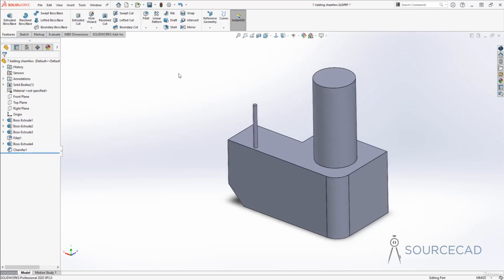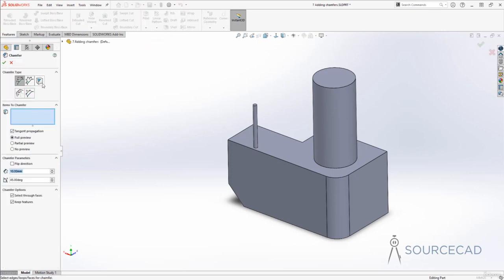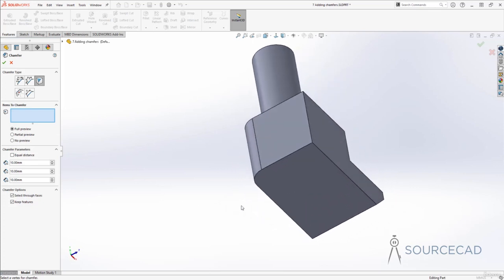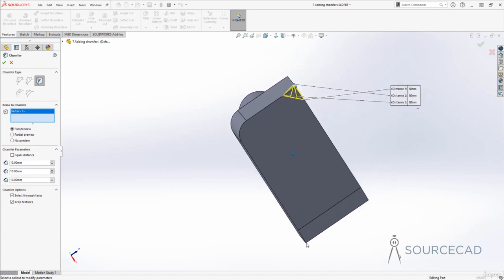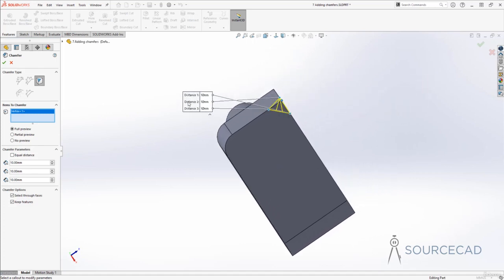And let's see what else we have. So I'll go to chamfer, and now we have this edge. And as expected, well, you need an edge. So here is the edge. I'll select that, and we have the basic edge chamfer with 3 distances here. Now the 3 distances can be changed from this palette, or you can change it from here as well.